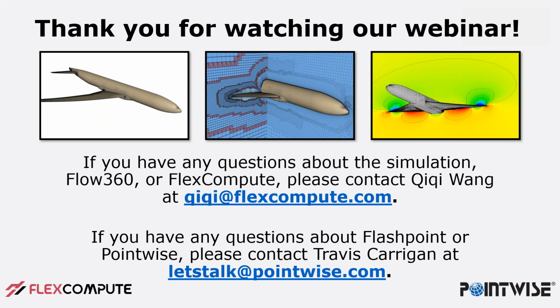Now, in an MRF situation, and we've done one recently, the FDA blood pump, you basically mesh each model separately. So that MRF interface needs to be a part of the models. You mesh each model, and then you use grid merge to stitch the two together. And that's how you can mesh multiple models with an MRF interface. It's a good question.